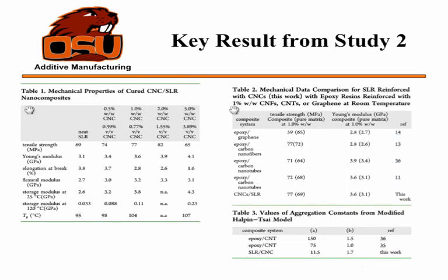The main thing was to identify what percentage of cellulose nanocrystals they can introduce into the epoxy in order to get good values for mechanical strength, and at the same time not lose the properties of the polymer, like its viscosity. They tried different percentage volumes like 0.5, 1, 2, and 5. It was seen that up to 2% was fine, but 5% was the limit after which you did not have a homogeneous distribution in the polymer matrix.